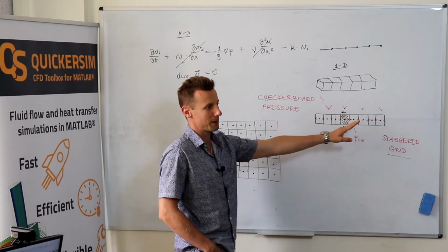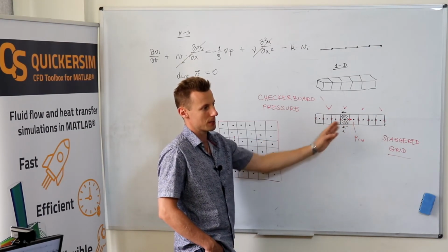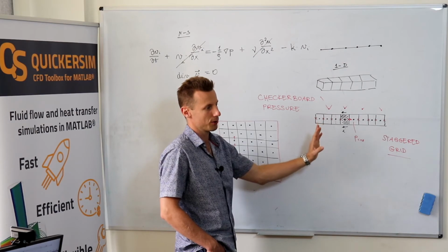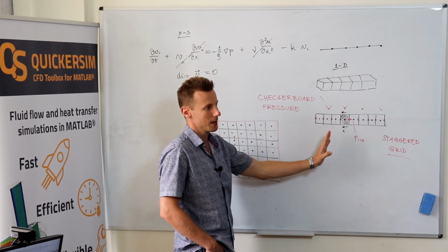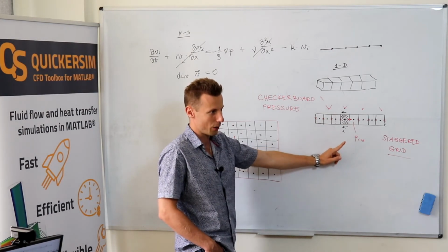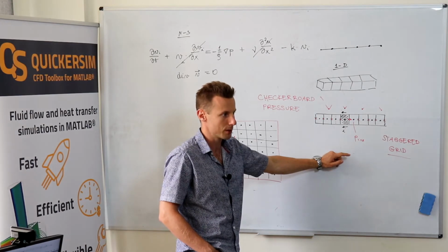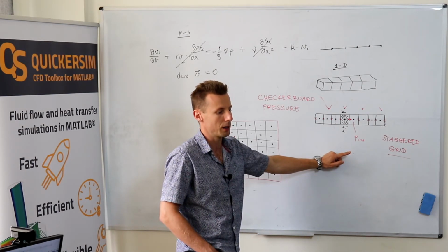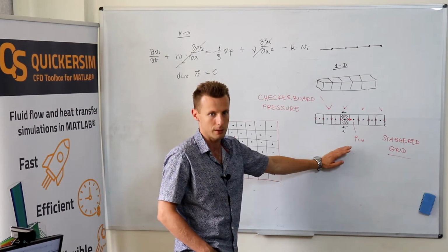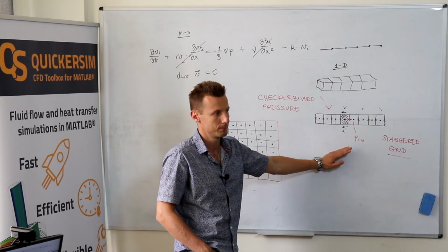Still, quite many problems can arise if you've got rapid changes in the flow velocity, or some transported quantities that you transport from one cell to the other. I want to mention the topic of limiters, but let's cover the limiters in one of the last lectures, not right now.